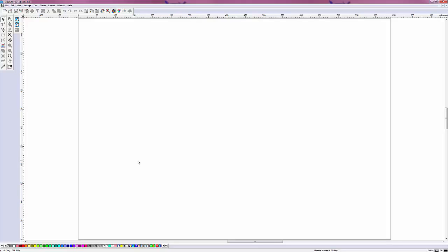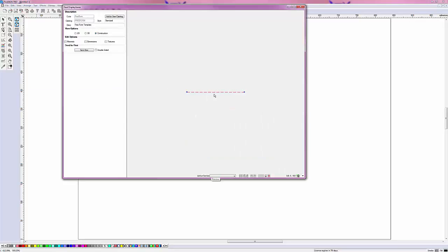As the first step in DisplayGenie's construction view, I will show how to make and fold a cardboard cube. We make a new freeform object, and this gives a baseline from which we start everything. Now, this baseline is currently 300 millimeters long, and I want a 200 millimeter cube, so I'll change that to 200. And you see it gets a little shorter.